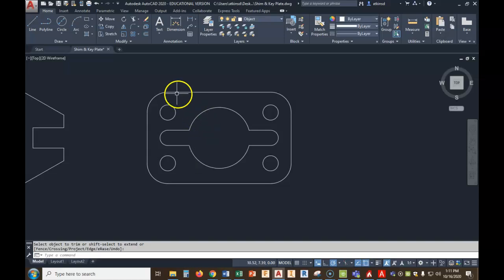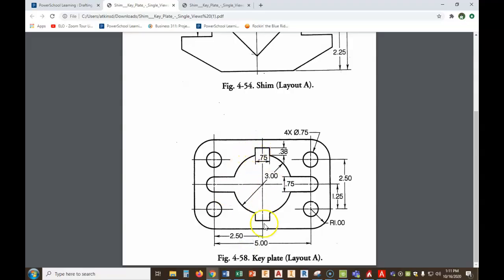But we're not done because we've got circles. And look what else we've got. This is called a key plate because these little notches here are called keyways. Now here's the deal with the keyway. This is important. If you notice, we don't measure from the edge of the circle right here or right here. We measure from where the circle and the line hit. So what we have to do is establish these 2 lines first. Well, let's draw us a line in the middle because we're going to need center lines here in a minute anyway. We'll talk about center lines in just a second.